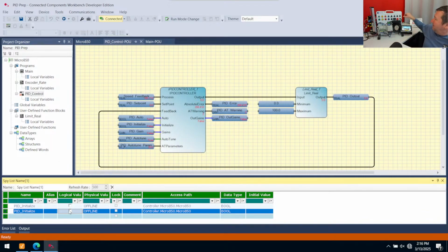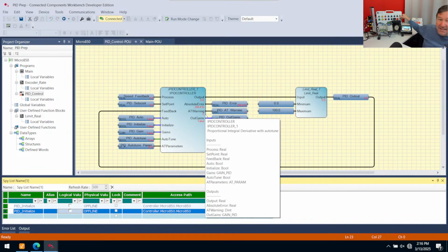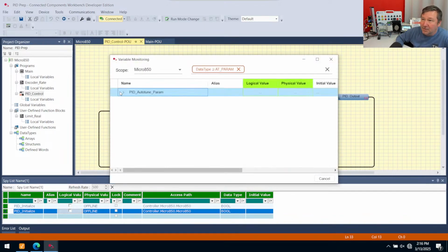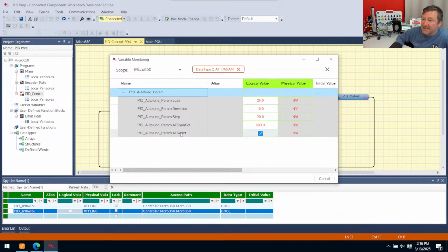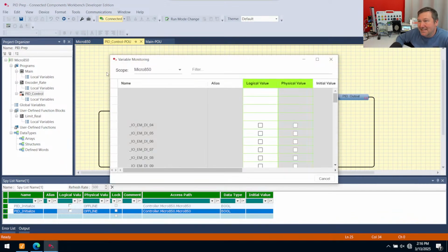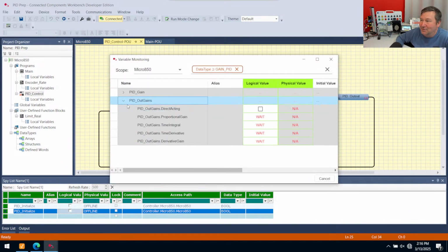No, so somebody one day is going to have to explain to me. So we have an auto tune of two. That means we're successful. Somebody's going to explain to me this whole craziness with this AT reset parameter here. But yeah, that's why I end up fighting it every time. So if you're struggling to get that two up, try auto tuning with this off and then turn auto tuning with it on again. As insane as that sounds. But okay, now we have our PID output gains, which embarrassingly I forgot to save. Hopefully they're about the same numbers.